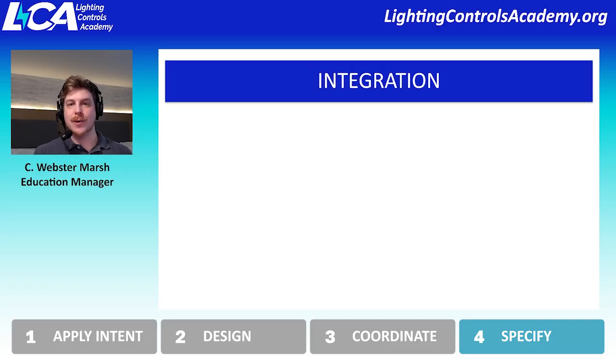Integration is a really important thing to identify as early as possible. What it does is it allows different systems to work together, and you might even find integration within the same system for the purposes of communicating between two unrelated devices, such as, again, DMX512 is a perfect example here. You're actually going to be integrating the DMX512 fixture into the lighting control system, because odds are that lighting control system is not natively speaking DMX512, but rather using a device that then integrates with DMX512.